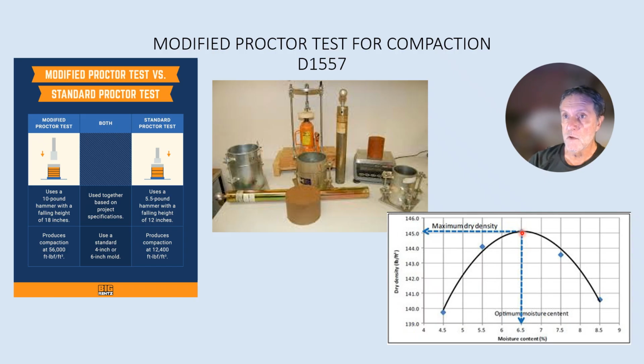And the rule of thumb, the standard, is you want to achieve at least 90% of that optimum or maximum density in the field through compaction by rolling over it with heavy equipment or using mechanical rollers, or sometimes even jackhammer type devices that can be manually used by an operator.